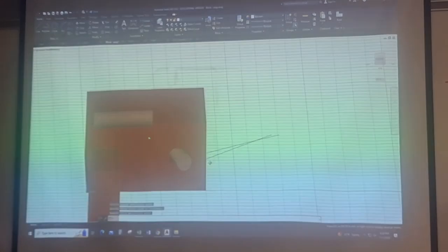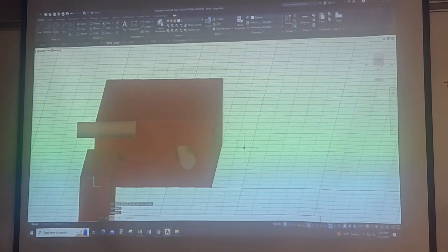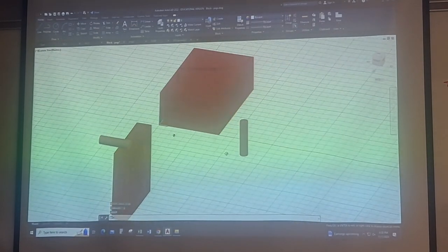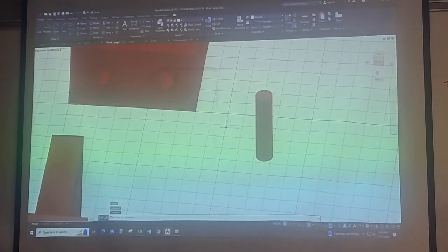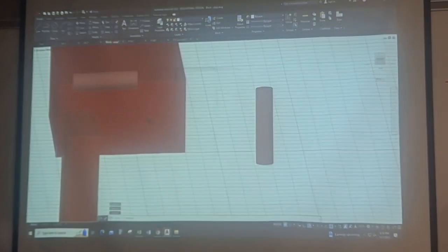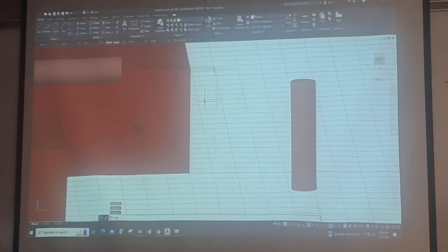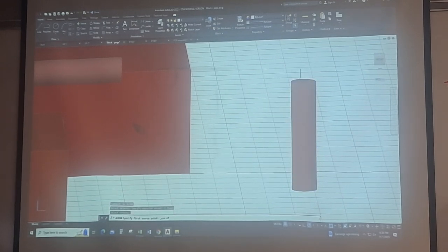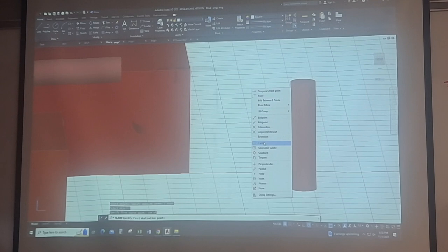Now the reason it did that was because, on that second and third points, I think I picked a quadrant over here and then a quadrant over here, which made it spin out. So that's okay, I understand, I know what I did wrong. I'm gonna go through it again, select this object, center up here, center back in there.